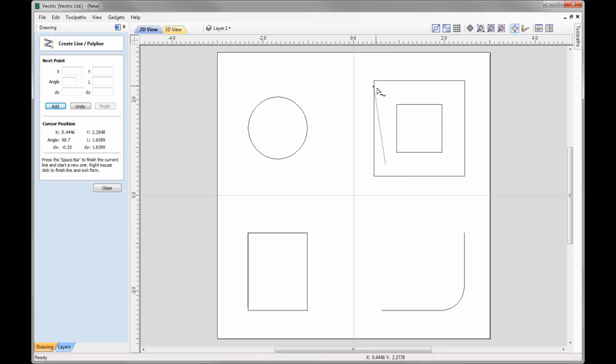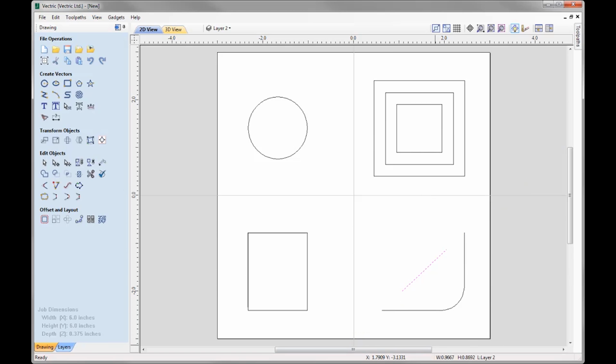So again, wake this point up, follow that back, and I've found the connecting line. Over to this side, wake this point up, and I found the center there, this one and this one, found the center there, and then I can click to finish that drawing. And the same applies to open vectors. For example, wake this point up, bring that along, and you can see that I can find the center of that line, or I could just connect anywhere between the two there, like so. And so Smart Snapping is a very powerful feature for us to create accurately aligned vectors very easily without the need to create construction geometry like you saw in this example.